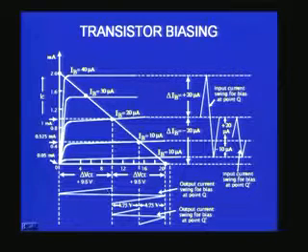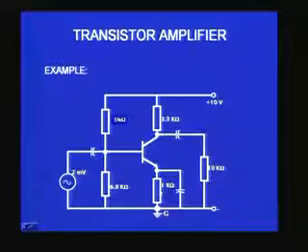This is a large signal which corresponds to the output. If I shift the operating point to some point here, you would find I will not be able to have perfect reproduction of the sine wave. If I give a large signal which is varying by 20 microamperes, you get only 10 microamperes available. Beyond that, there won't be any signal, therefore the signal will get distorted. That is the reason why I say I must always bias nearly at the midpoint of the load line. Then I will have equal excursion possible on both sides of the load line, and therefore I will get a reasonably good amplifier.